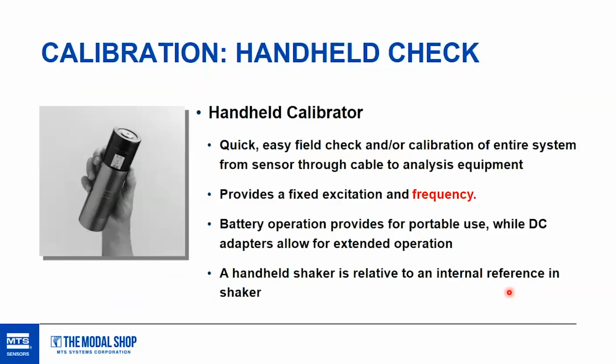These guys are really handy if you are setting up a series of test equipment. You have different data acquisition systems, you have different signal conditionings, you have gain in your system at certain points. It's often used as a sanity check, one of these guys here, to see if your channel is in fact connected to the right cable, to the right signal conditioner, with the right gain, ultimately back to the data acquisition system with the correct sensitivity factor entered in for that channel, so that the measurements that you're taking are accurate.